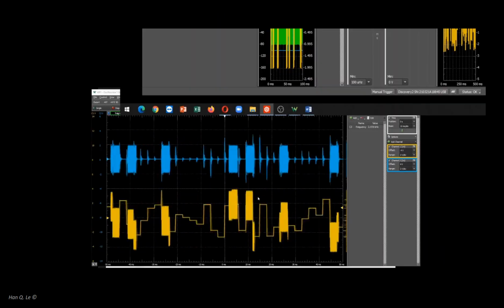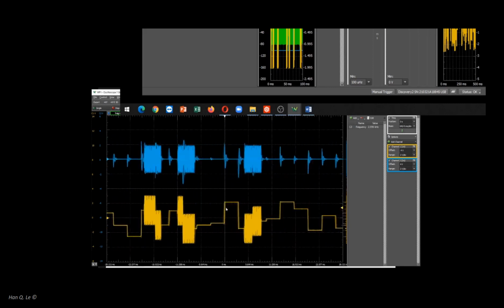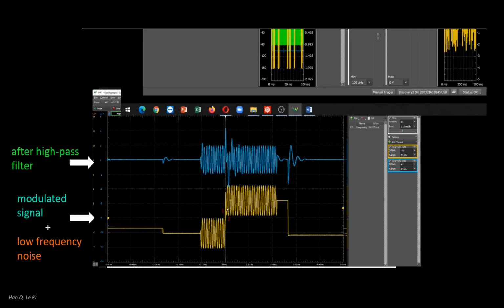This is a zoom in to see the filter performance. Even as a noise step vertically splits a data pulse into two, the filter passes the data pulse largely intact with just a step function spike. In the frequency domain concept, if you have learned Fourier analysis, the spikes represent the noise's high-frequency spectral portion that is passed through by the filter. The higher the noise fluctuation is, the higher is the spike.